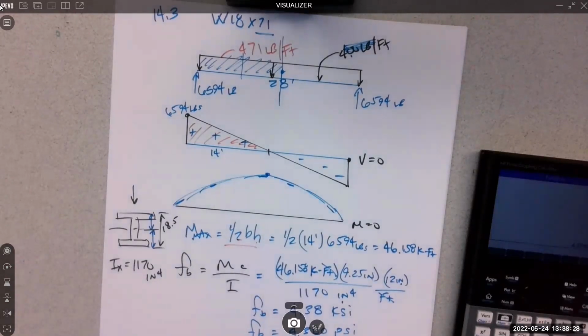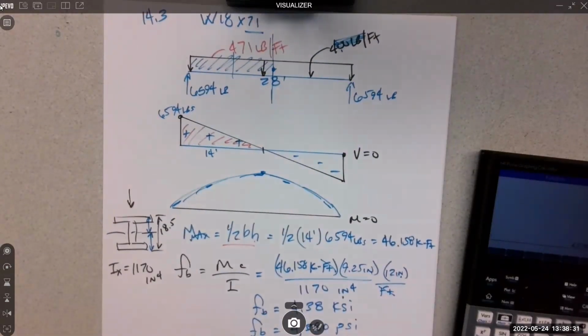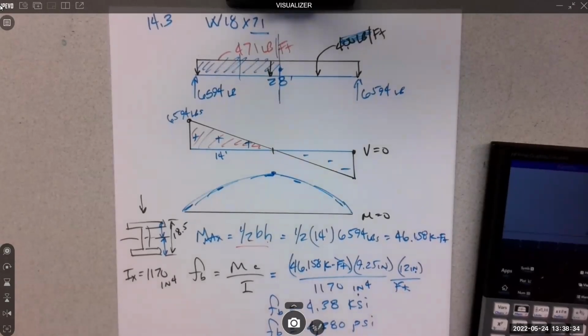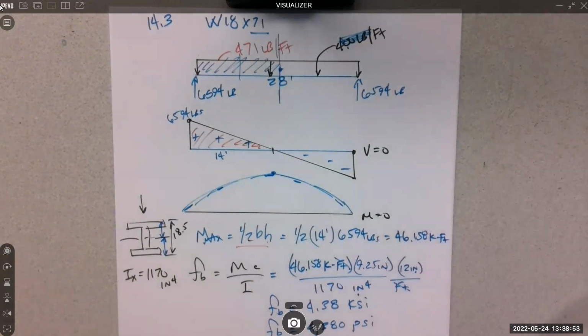Okay, so structural steel, if we don't know its exact properties, typically is an A36 steel, 36,000 yield. So we're at 4,380. We're magnitudes or factors of safety under the 36. If I take 36 and divide the 4.39 into it, that's 8.22. That's a factor of safety of 8 on this design.